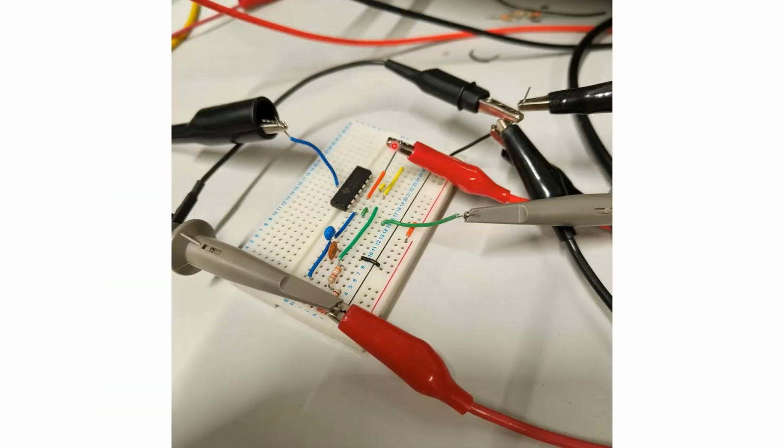This here is connecting up the circuit. So here, this red wire is connected to orange. That's the positive 15 volts. This is the negative 15 volts connected to blue. These are all the ground cables connected up to that ground wire. And this here is the input signal coming from the signal generator. This probe here is picking up the input signal, which will display it on the oscilloscope, and this probe here is picking up the output signal.